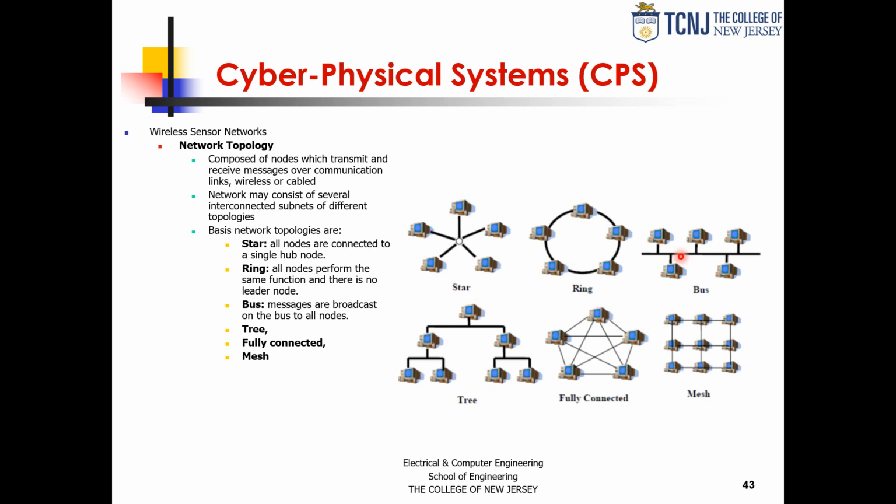For example, at the physical layer of Ethernet, the Ethernet physical access chips, what they do is they transmit. And electrically, the network is designed so that you can transmit and then listen. If what you listen is what you sent, then you know there is no collision.